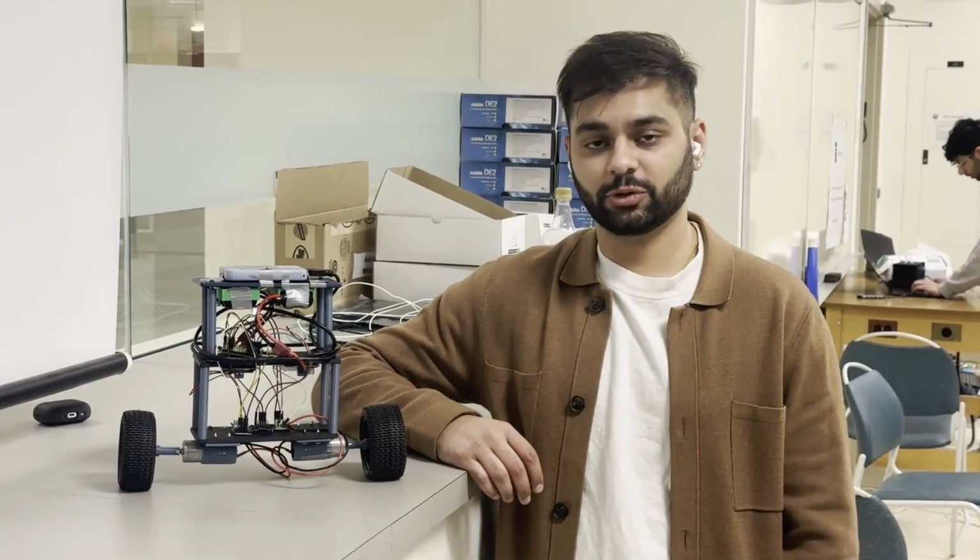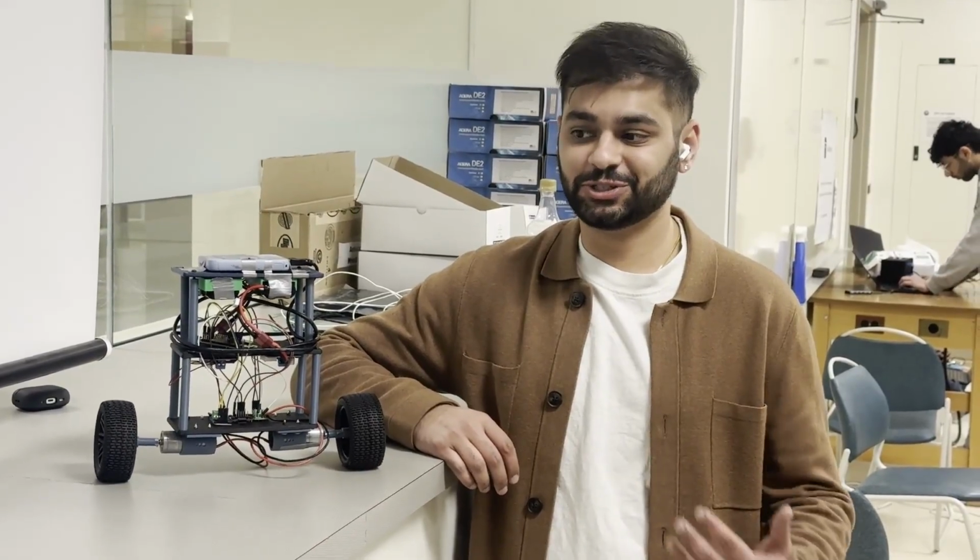After some time tuning the PID, Cypher successfully balances from startup within 5 seconds and recovers from angles of 15 degrees. It can continuously run for 12 minutes on a full charge and adjust itself dynamically. While minor oscillations remain during aggressive pushes, the system is robust and responsive, just as we planned.